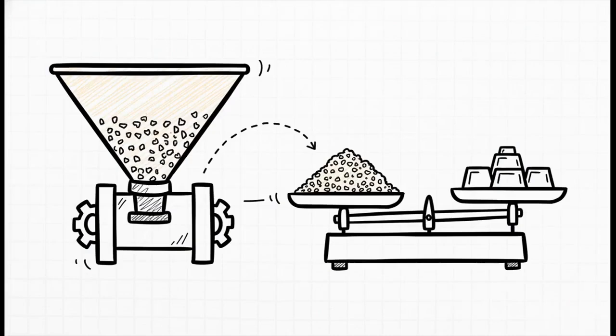The formula is a breeze. Bulk density equals the mass of the sample divided by the volume occupied. You express this in grams per cubic centimeter or grams per milliliter, but why do we care? Well, out in a factory, plastic granules are fed into massive processing machines through large metal funnels called hoppers. Knowing the bulk density tells the machine operator exactly how much physical weight of plastic will actually fit into that hopper's volume. That is completely crucial for setting up continuous, uninterrupted machine production.